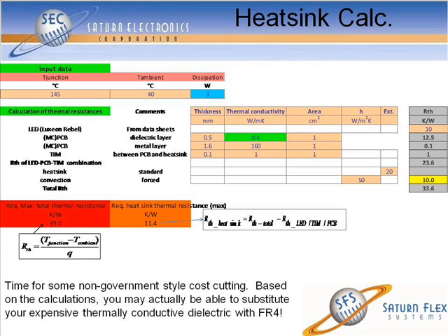So I just threw in from the data sheets the thermal conductivity value of FR4, 0.4 watts per meter Kelvin. And it seems to work in this calculation. Now remember, we're talking strictly thermal conductivity. When you talk about calculations for heat spreading, they're much more intricate. Those are where everyone has slightly different models. So I'm not saying that it's a catch-all solution, but, heck, it's worth a try.